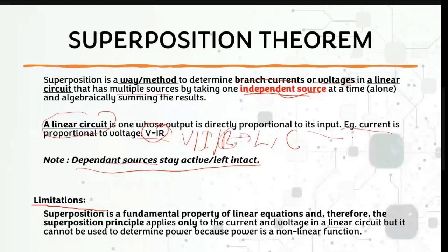Because power analysis in a circuit requires considering all sources and components simultaneously and applying the appropriate mathematical relationship. You know that for power we have the multiplication of current and voltage, so we call this a non-linear function. For a non-linear function, we cannot use the superposition theorem.